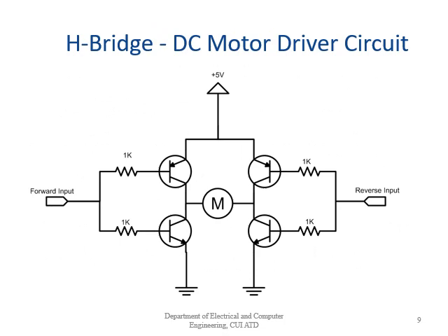Okay. So this is the circuit of a basic H-bridge with 4 power transistors that provide current for the motor. In this circuit, you can think of the power transistors functioning as on-off switches. So these are the on-off switches 1, 2, 3 and 4. The 2 digital logic level inputs, the forward input and the reverse input, turn the transistors on and off. In the center, the circle M stands for motor. This is the DC motor device being driven.